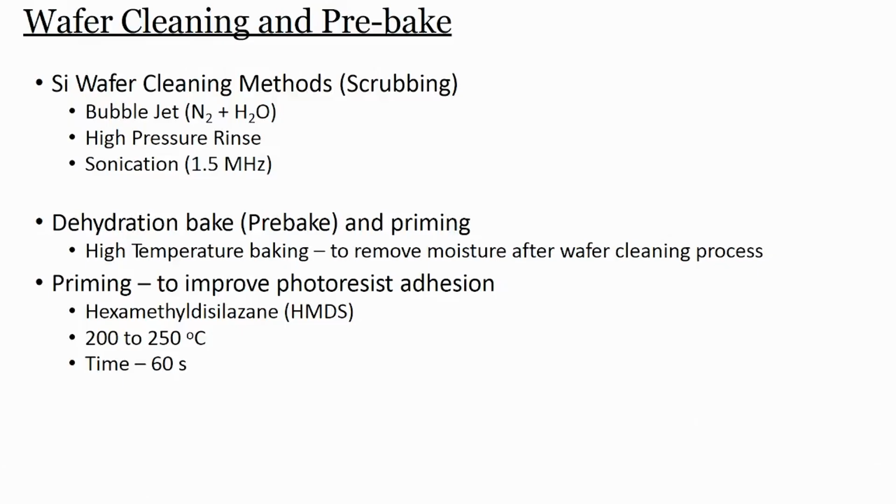How the wafer is cleaned and how the pre-bake is done. The silicon wafer can be cleaned by several techniques. One is bubble jet, where you use nitrogen plus water in a jet formation, and you can use a bubbler. So, you can clean the wafer.